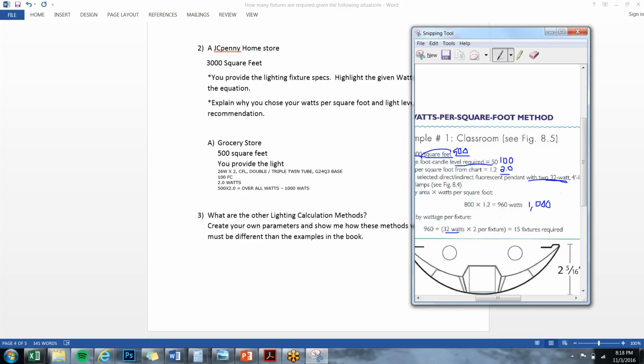So we had that our light fixture over here is 26 watts, but we have 2 per fixture. So it's times 2. We have to remember to do this step. That's different than the second example that I showed because there's 2 per each of those square fixtures. We have to incorporate that 2 part.